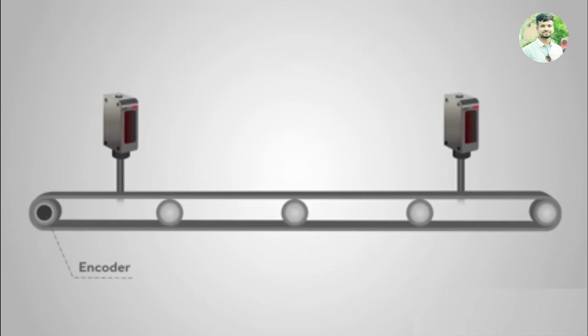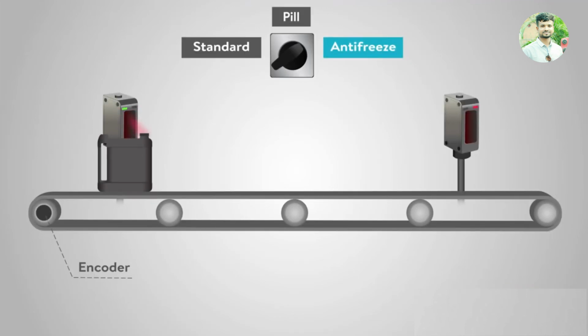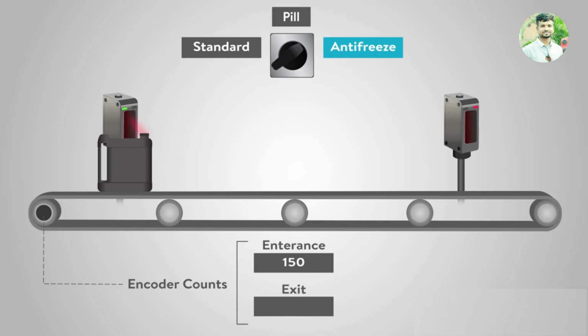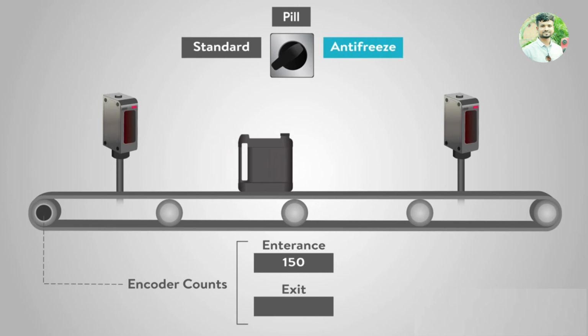An encoder, some code, and a selector switch for a setup mode. To set up, insert your product, in this case the industrial bottle. You make sure to feed cap first, and it must contain a foil. Your program reads an edge on the sensor, records an encoder reading, and determines that this is a cap and records that fact. Your program then records another edge and determines that it is not a cap and must be some other acceptable part of the bottle, possibly a handle.